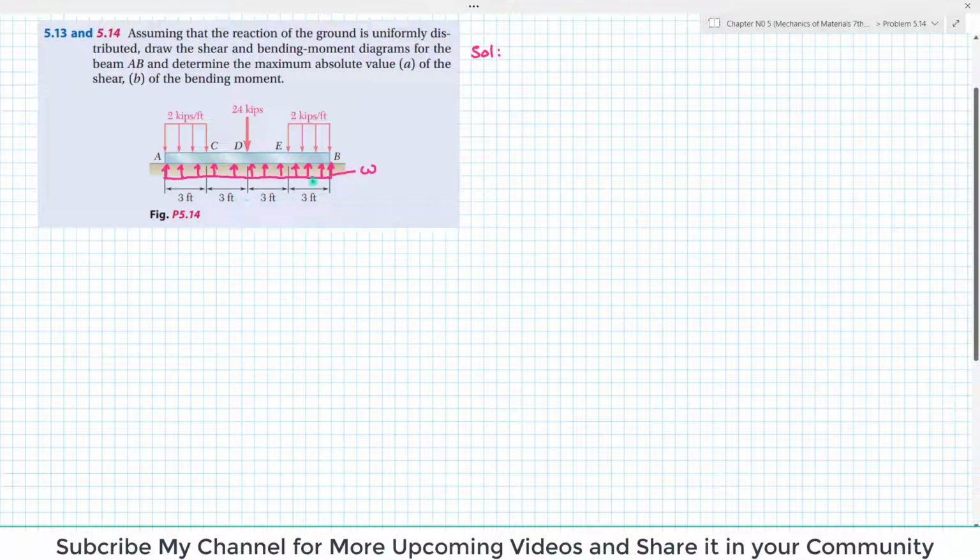12 feet, clear. We do not know this W, so first of all we will find W by using the equilibrium condition, that is, the sum of all forces along the y direction must be equal to 0, taking upward force as positive. From this figure you can see this is a uniformly distributed load of 2 kips per feet, this is a distributed load, and this is a point load. So we will convert this distributed load, this load and this distributed load into point loads.